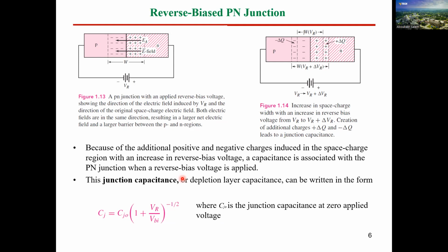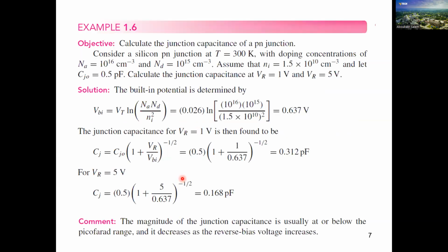It's not that important in our calculations for the time being, but what we need to understand from this part is: if you apply a reverse biasing for our PN junction, the depletion region is going to increase, no current is going to flow, or let's say only leakage current will be allowed to flow. Leakage current, we will give a definition for later on. It's a very, very small amount of current. And also you will have an increased capacitance, or junction capacitance, due to this reverse biasing. And this is a direct example to know how to apply this relation to our case.